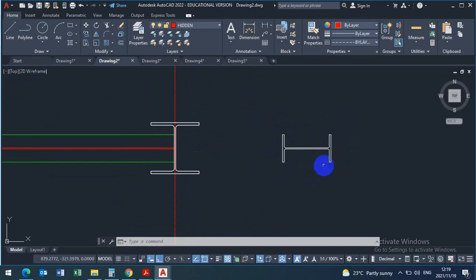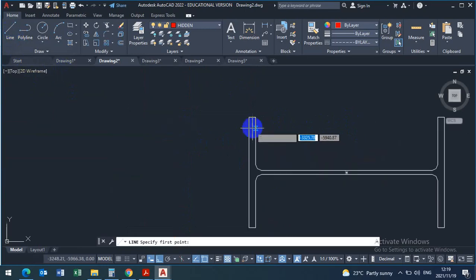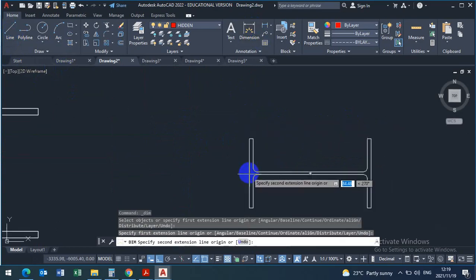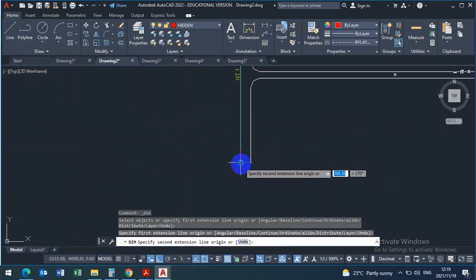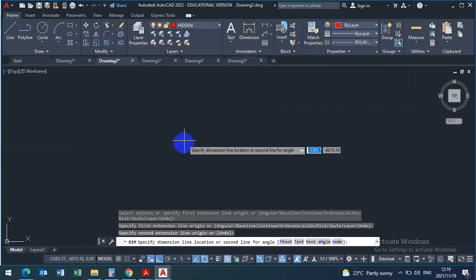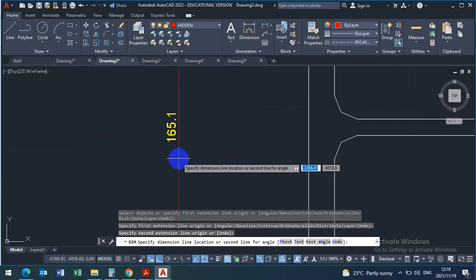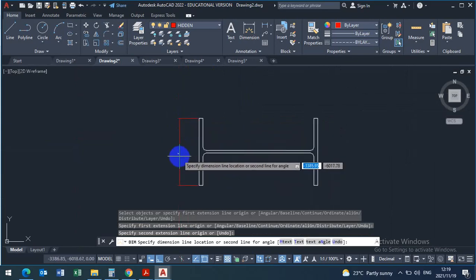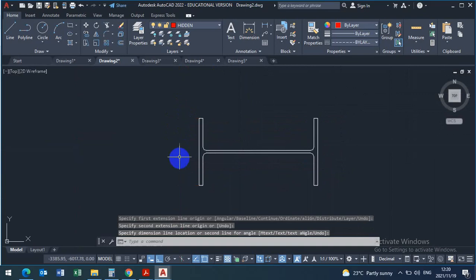So you can now draw the end plate, but we remember that we always have to go outside by 10, okay. So whatever this is, let me measure this. The beam is 165.1 plus 20, you can say plus 20, 10, 10 for the welding, okay, for the plate, 10, 10 out. So I'm going to draw.